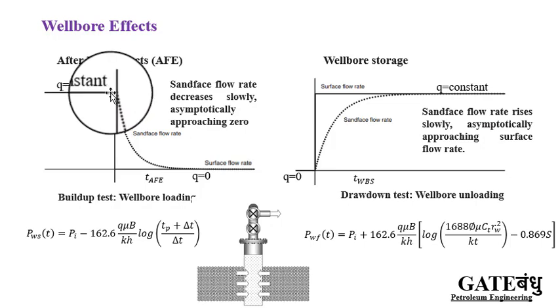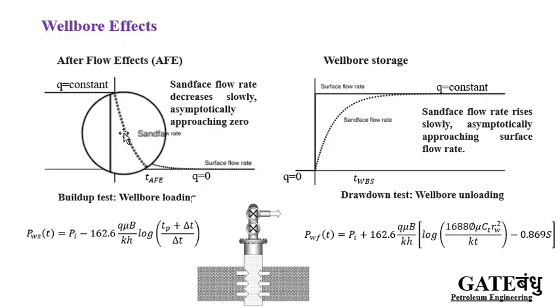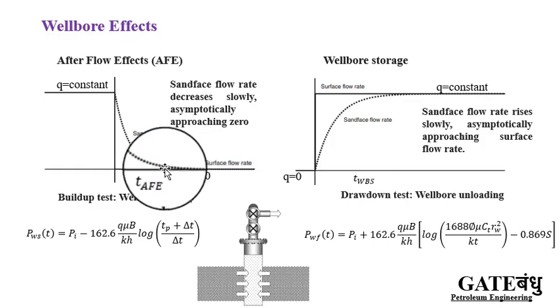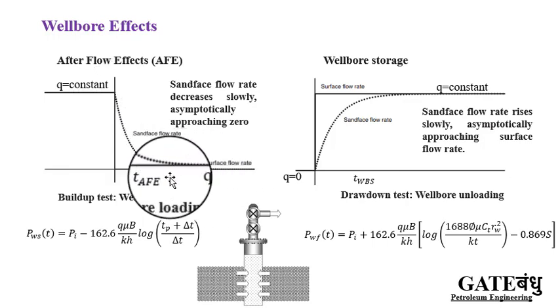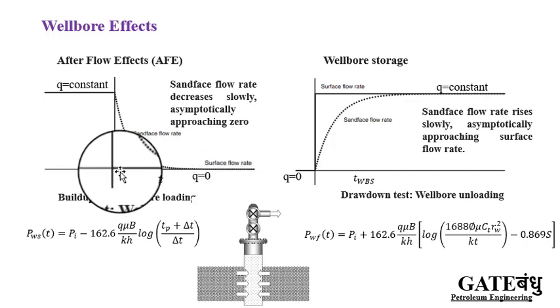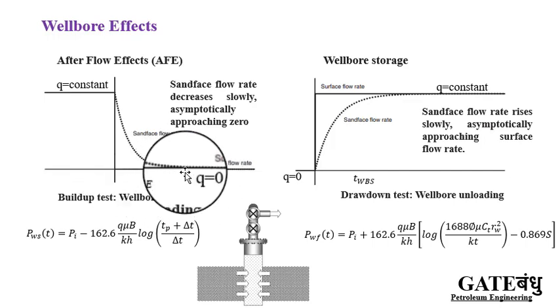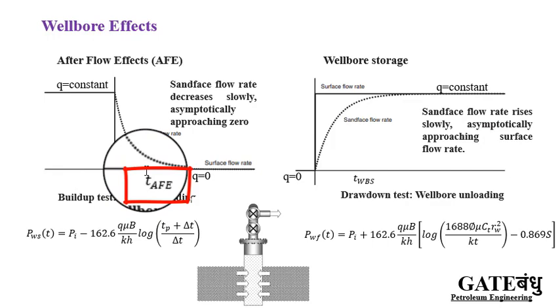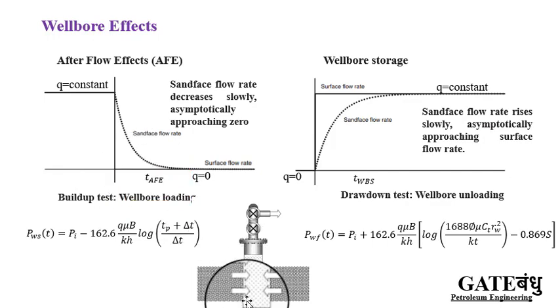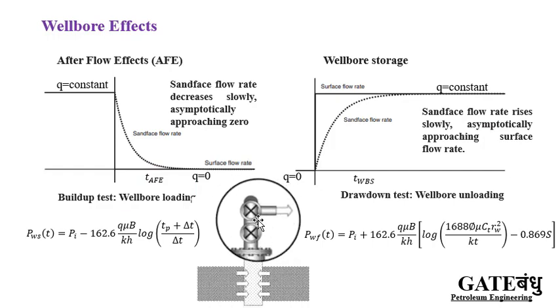Until the wellbore gets filled completely, this Q at the subsurface will not go to 0, but it takes some time to do this. So the time when we close the well at the wellhead, to the time when the flow rate at the sandface goes to 0, this time period we call the time of afterflow effect. So you understand, only the wellbore volume that is there is providing space for fluid to enter even when we close the well from the wellhead.